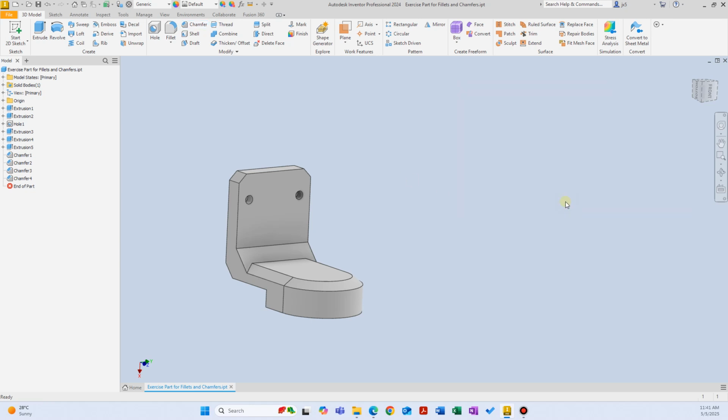And one little detail, I think I mentioned this before, but I'm going to say it again. Try not to be too generous with fillets and chamfers. If you're going to get this part 3D printed, you don't have to worry about it. But if you're going to send this to a machine shop, if it's something made out of aluminum or stainless steel, and you add so many fillets with different radiuses, different distances, then those are each different machining processes, and that's just going to increase your price. So try to use fillets and chamfers only as they are needed.